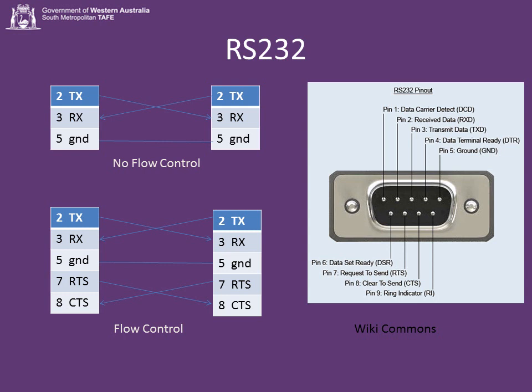With flow control, you have a couple of different extra wires. I don't remember the last time I saw anything using flow control. So typically for RS232, you need 3 cores. Anything will do. It's a very, very limited distance though. You'll be lucky to run it more than 3 meters.